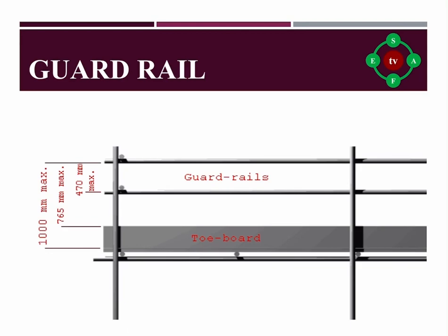Guardrail height. Guardrails are visible and physical barriers used for preventing falls from heights. The height of the scaffold's top rail that was manufactured and used in service should fall between 38 to 45 inches.